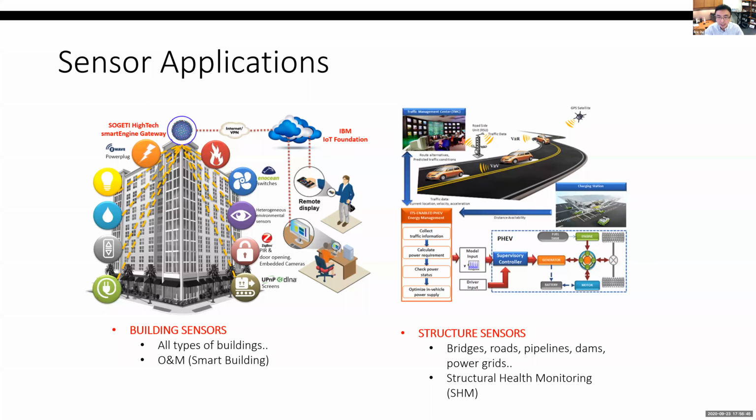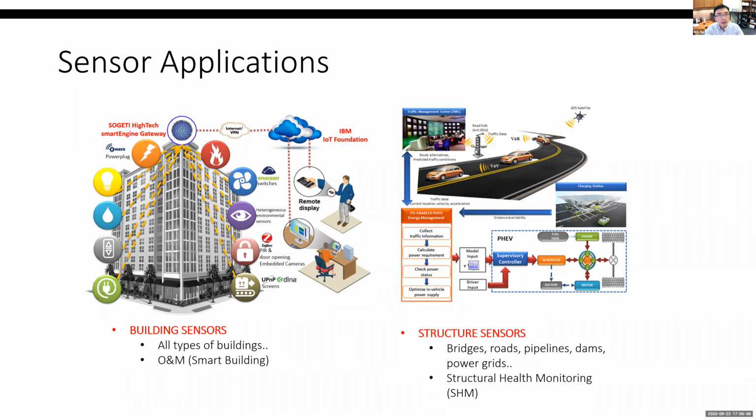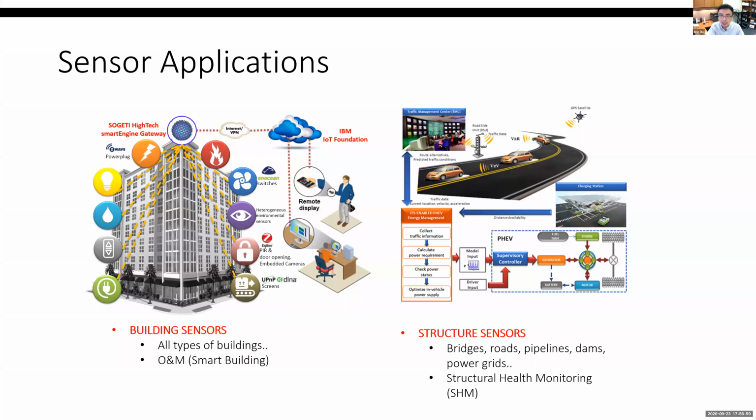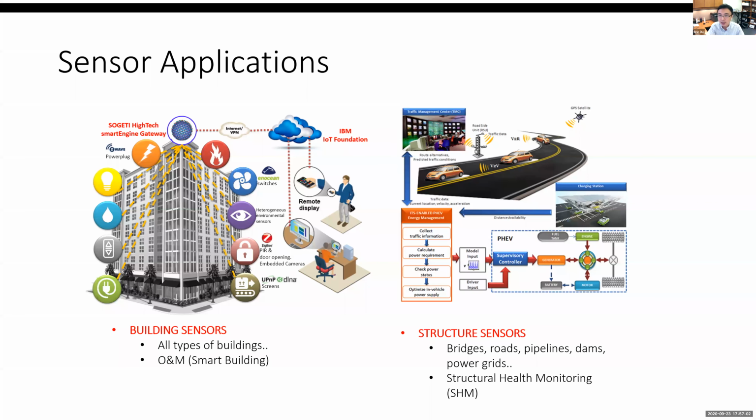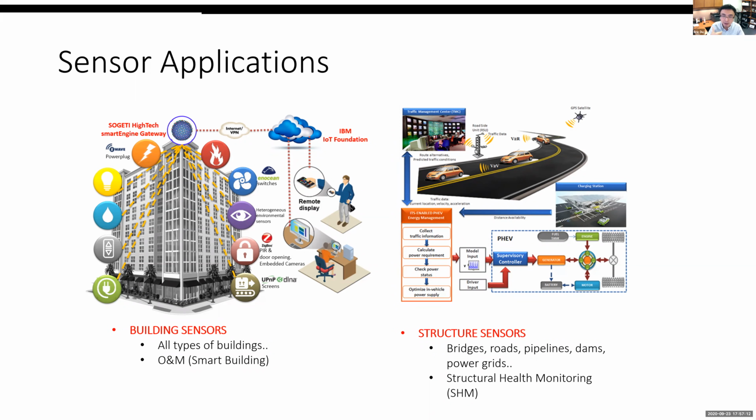Some of the sensors are embedded as well. I know there has been research where they embedded chips inside the concrete. The chips serve as reinforcement as well as passive sensors: if you use a reader, the reader sends energy to the chips, and the chips read the internal strain, like tension or compression of the concrete, and send it back to the reader. So it's actually very convenient.